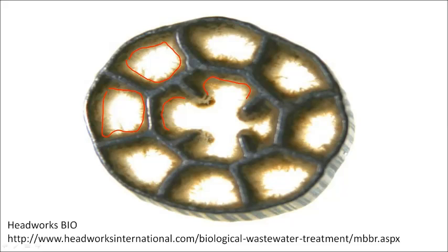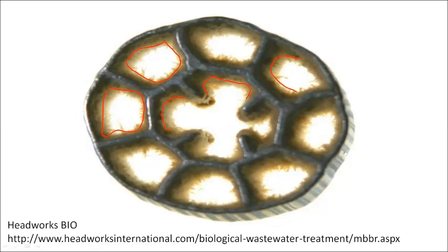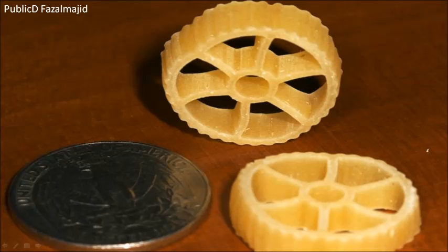So over time, as this biofilm begins to accumulate the different types of organic and inorganic nutrients that are present in the wastewater, the concentration of those nutrients in the water begins to decrease. And that biofilm continues to grow. It can become problematic if this biofilm gets too thick and clogs the matrix, because then the water doesn't go anywhere, right? And then they have to be cleaned. So this thing, yeah, I don't think I can eat rotelli pasta anymore after seeing this picture, because now I'm just going to always picture these as being covered in biofilms on the inside.